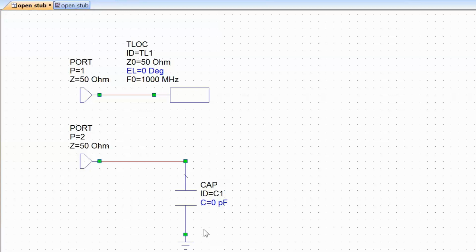When we look at the capacitor here, we are saying that the capacitance is 0 picofarads. This means that the plates of the capacitor are so small that they can't hold any charge at all. It is very much like each plate is like the end of a wire. And there are these two wire terminations which represent the two plates, which can't really interact with one another because they can't hold any charge, and hence there can't be any displacement current between the two. So for a 0 picofarads capacitor, we assume to have effectively an open circuit.